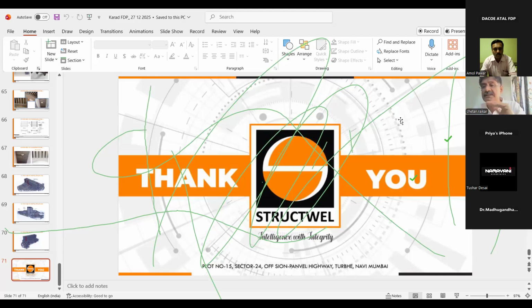So grade 3 structures in Mumbai we are allowed to reconstruct but use the similar features. Grade 2 you are not allowed to reconstruct but make certain modifications. Grade 1 you are not allowed to make any modifications in the structure, and any technique of restoration or repairs you do, it should not be glaringly or prominently seen.